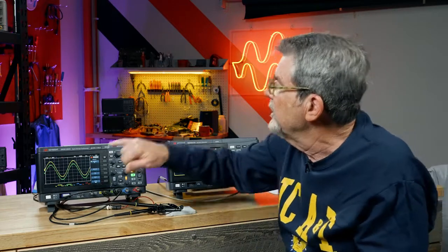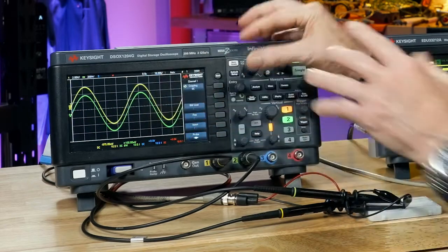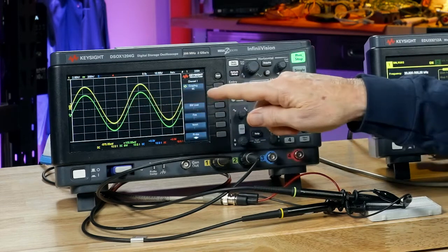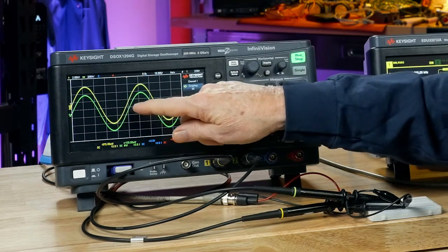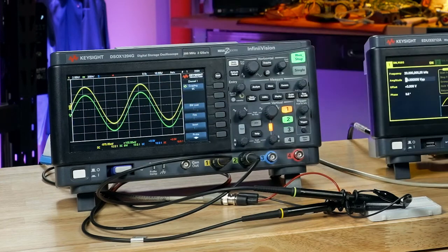What about timing? This number up here, notice if I change the time scale, this one also changes, tells me what the horizontal scaling is. So what is the period of one cycle? I can see that it's about 1, 2, 3, 4, 5 divisions wide times 10 microseconds per division tells me that it's 50 microseconds for one period. If you take the reciprocal of that, that tells you what the frequency is. It's 20 kilohertz. And that's exactly what I have set as the output of the function generator.